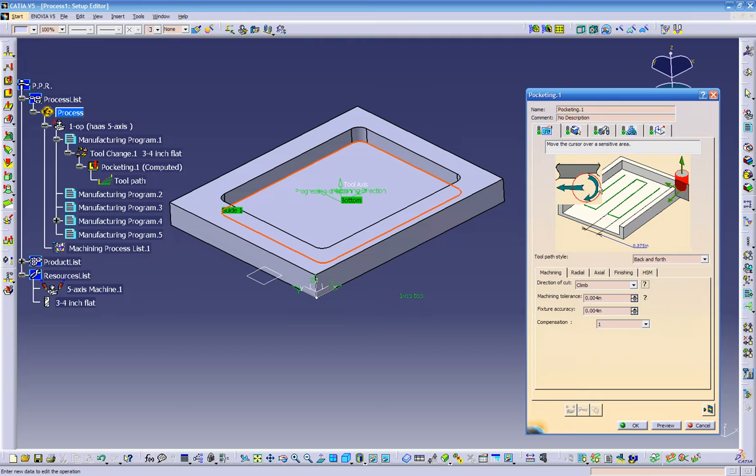So the end mill rotates clockwise, and it's moving forward this way. See the arrow going this way, and the tool rotates this way. So everything is climbing. I'm pretty sure that all the programmers out there know that most of the programs need to be climbing. Rare we find programs that we get a nice finish using conventional. So I very rarely use conventional. I always leave this on climb all the time. I never change it. Over here is the tolerance. You can see over there.